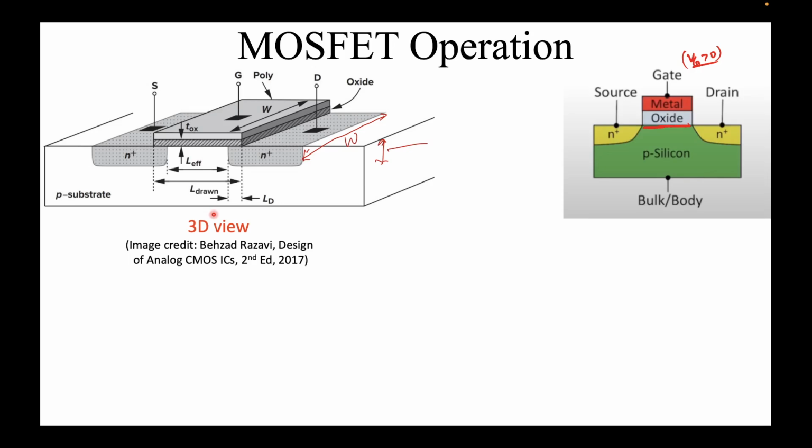Okay, so hence you see many other terms, like this, how they are making this contact. Okay, we'll not go into that, but this is the diagram that we keep on repeating, just a schematic to show how it looks in 3D, right? And for a MOSFET, we'll be talking about the 3 regimes. The 3 regimes that we have are switch off or off, second is the linear regime, and the third is the saturation regime.